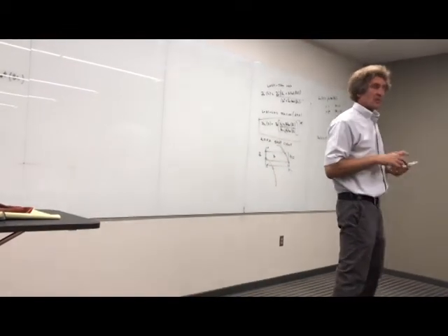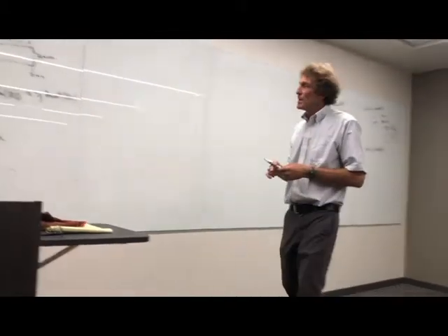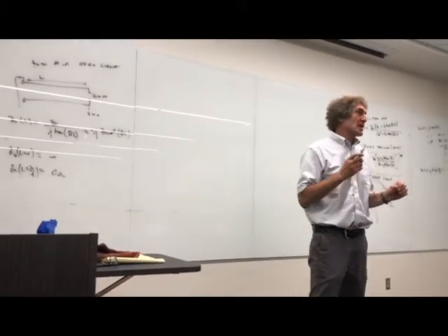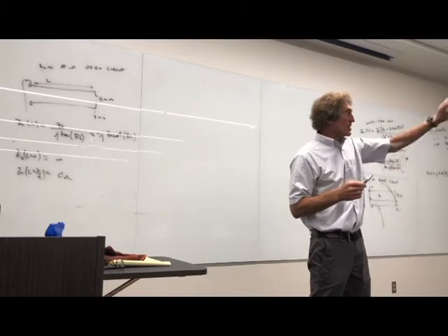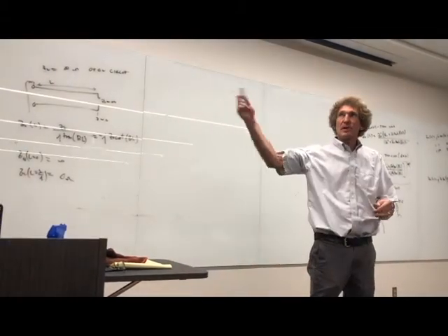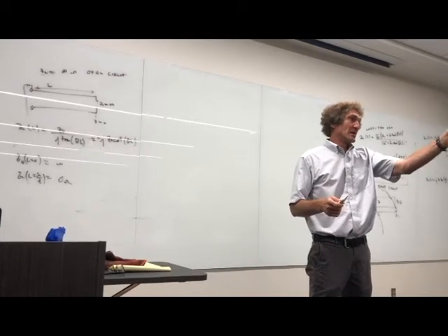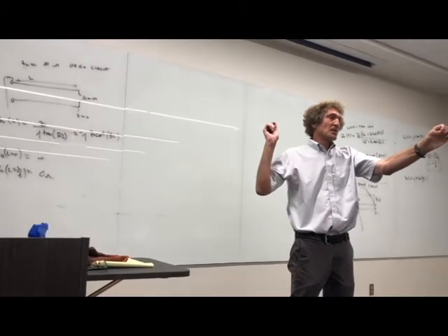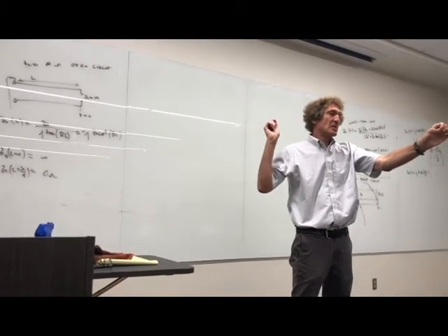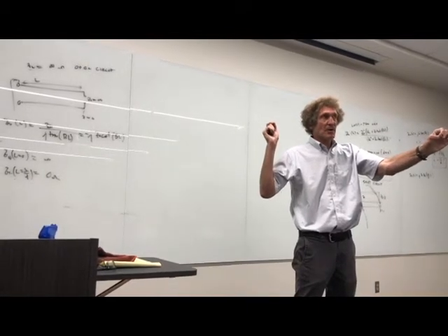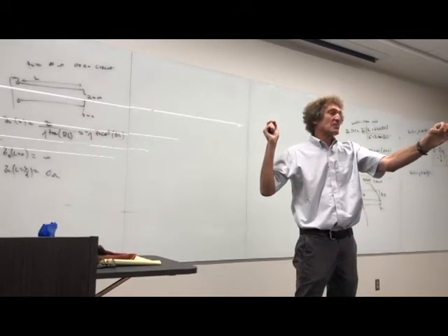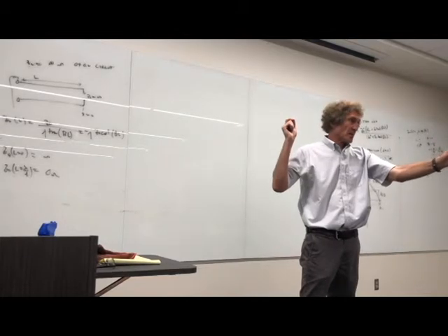Now, most of the time your load is a 0 or a short, but when we're measuring electrical distances, if you've got wires squirreling around behind the walls, you can always take the output point and short it, and then we'll show you how to do something called TDR, or time domain reflectometry measurement. We can do this with time or frequency, and we can figure out the electrical length of that line very easily. You all know what I mean?